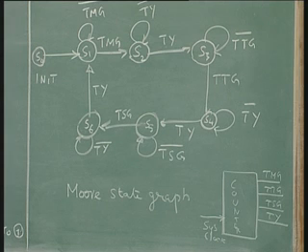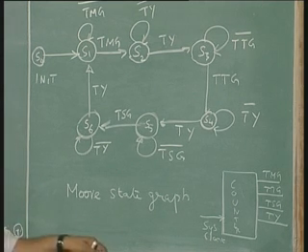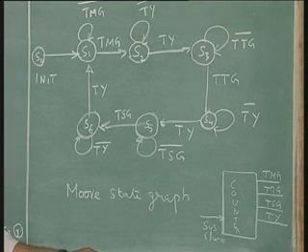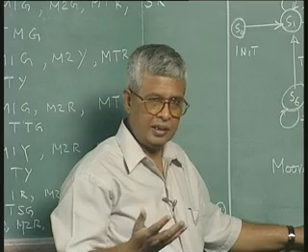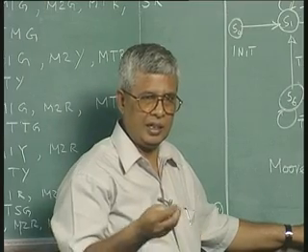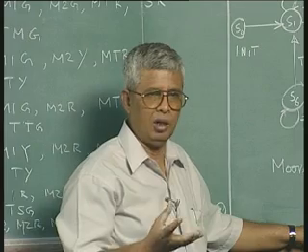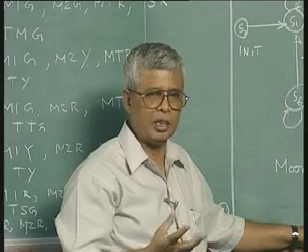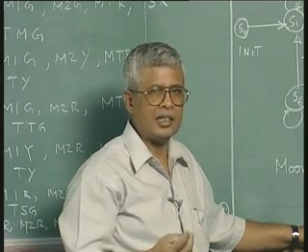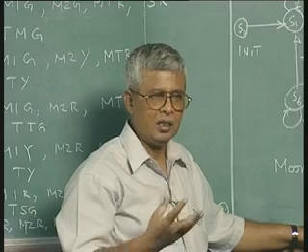So, you can switch off the power, or you can define a state called initial state, in which you can have a blinking red, something like that. You might have seen it on busy streets late in the night: in the main street the yellow will blink, which means proceed cautiously, and in side streets red will flash, saying stop and go.